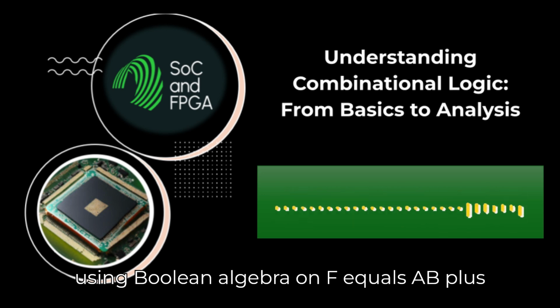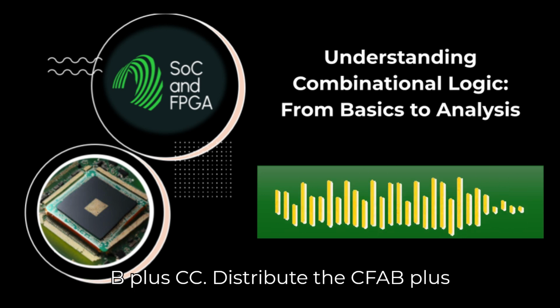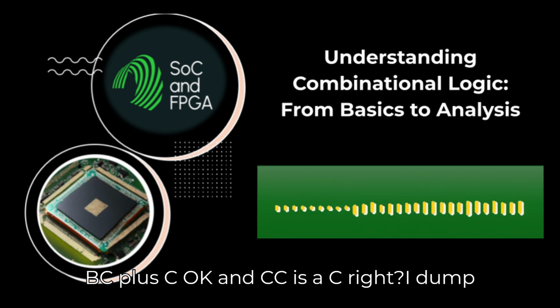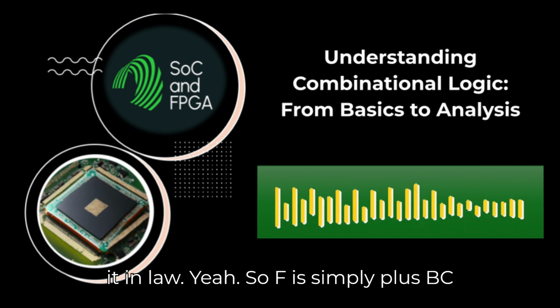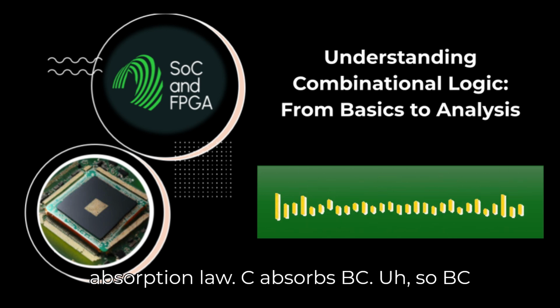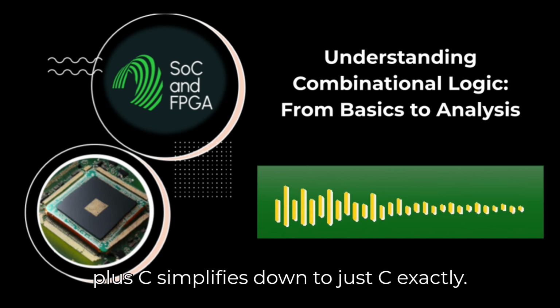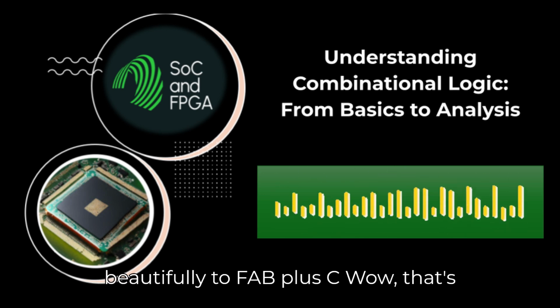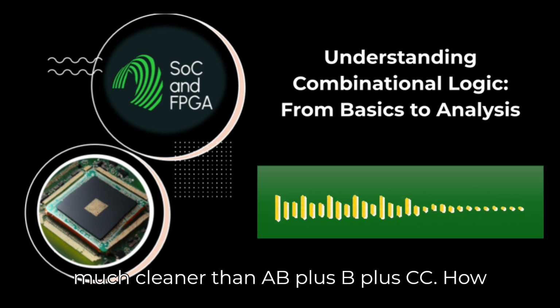Using Boolean algebra on F equals AB plus (B plus C)C. Distribute the C: F = AB plus BC plus CC. Okay, and CC is just C, right? Idempotent law. Yeah, so F is simply AB plus BC plus C. Now look at BC plus C. That's the absorption law. C absorbs BC. So BC plus C simplifies down to just C. Exactly. So the whole expression simplifies beautifully to F = AB + C. Wow, that's much cleaner than the original.